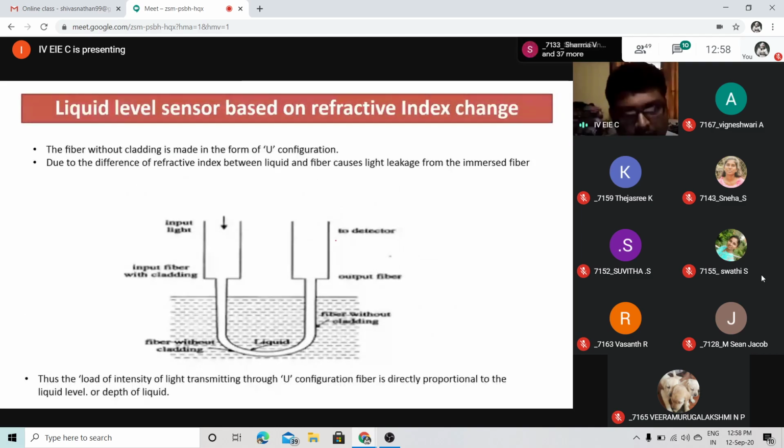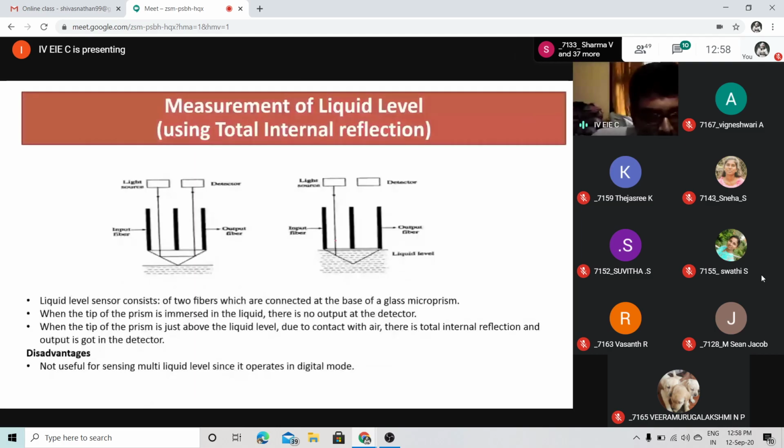In the first diagram, you are going to have a microprism. That is the working logic, where this microprism, which is present here, is going to support me with total internal reflection. So if there is no liquid, my light source, which is focused through my fiber optic cable, will successfully have total internal reflection, and my receiving cable will receive the light intensity to the detector. Okay, now the connection is complete. The light energy passes through, gets totally internally reflected, reaches my detector.